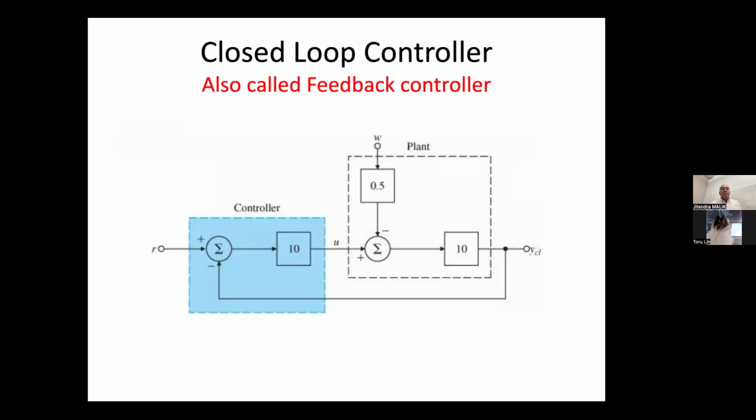Now, what's the idea of closed loop control? Closed loop control is that you look at your speedometer, right? You look at your actual speed, and you have in your mind the desired speed, and you measure the error. This is the key concept of control. There is a desired speed, there is the actual speed, you make a measurement, and the difference we call the error.